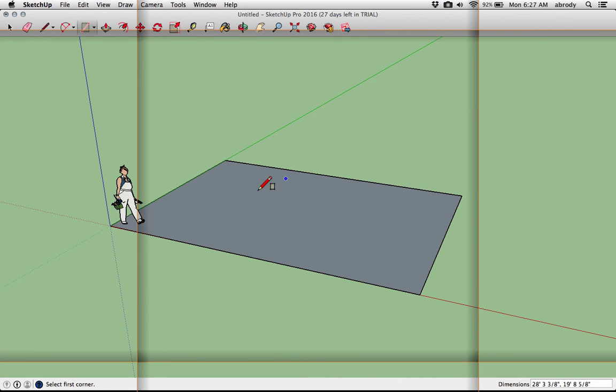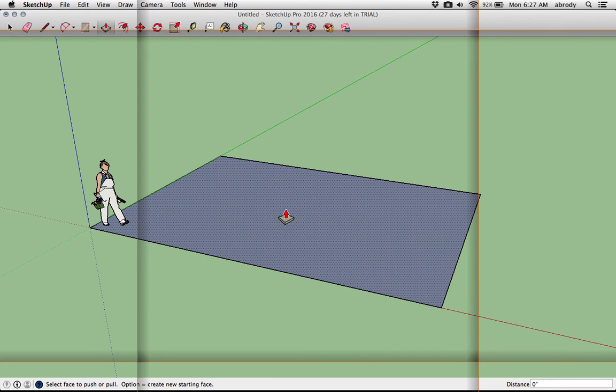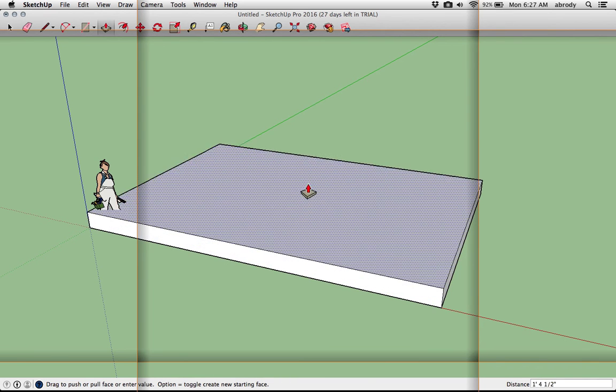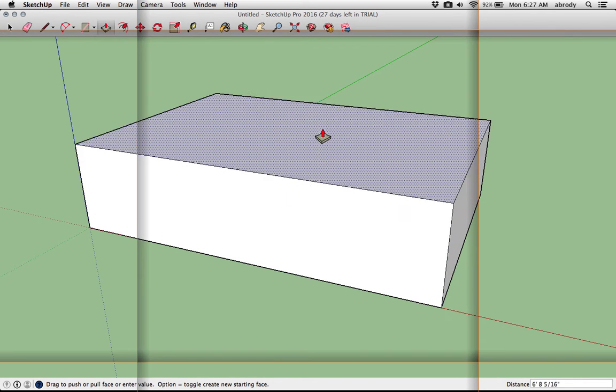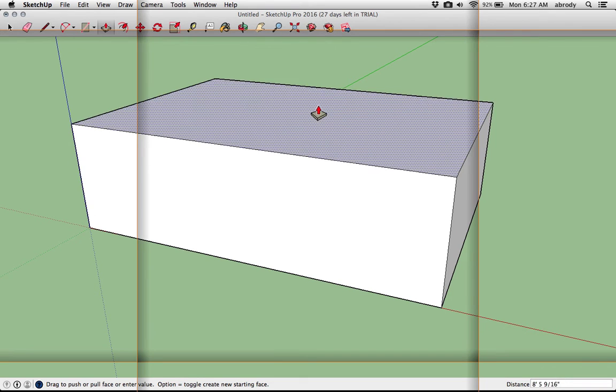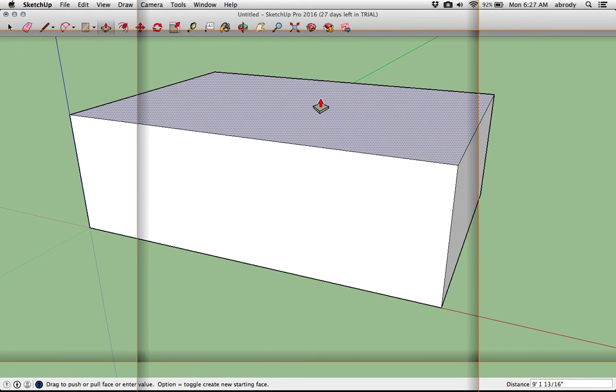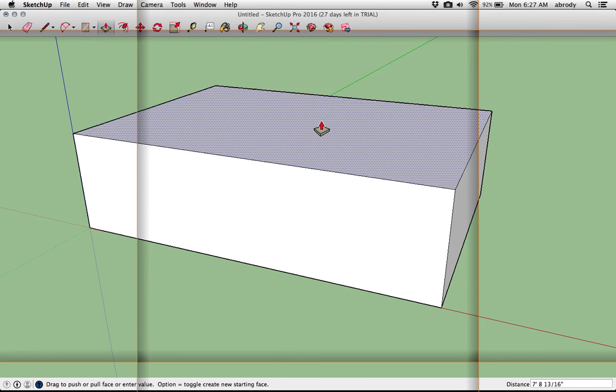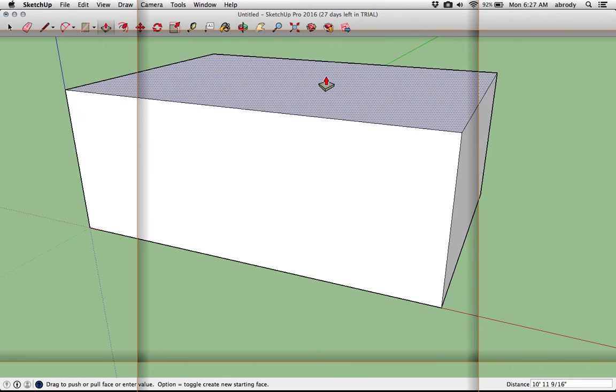So now that I have this lovely rectangle, I can use another tool right next to the rectangle. It's called the Push-Pull tool. You just click on the tool, and a few of you I may have shown you this in class when you were adding furniture. With the Push-Pull tool, you just click on a surface, and it grabs the surface. And I'm not clicking and dragging. I just hit the mouse button once, and I can push-pull up and create a box.